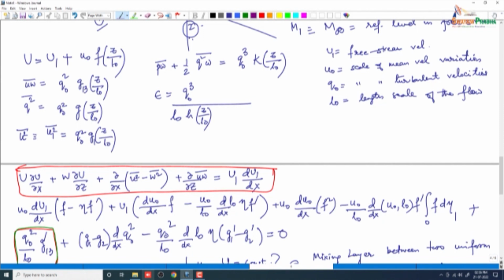One of the reasons, for example, is that the Reynolds stress doesn't develop suddenly, right? It does take time to develop, and it takes time to decay. At a particular location, although we've said this is moving equilibrium, the Reynolds stress existing at that location and time, how much it is spreading and at what rate, depends on what was happening earlier, on conditions upstream. So although there is symmetry of the mean velocity distribution locally, it doesn't mean that it was always the same, in terms of the history of how the flow has been developing since it started out. Those are a few pointers to this whole discussion.